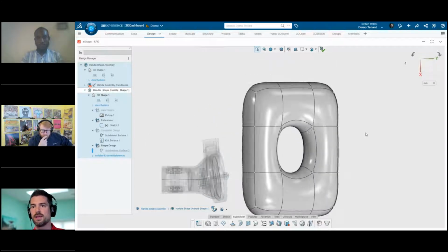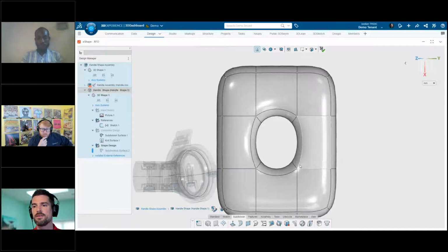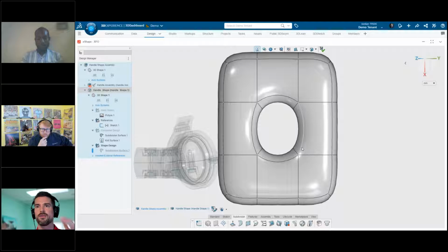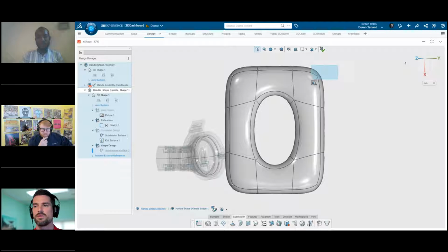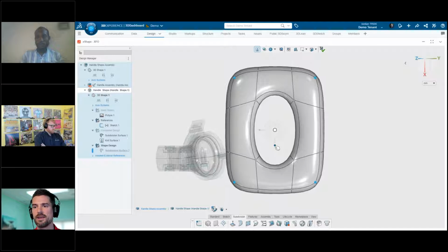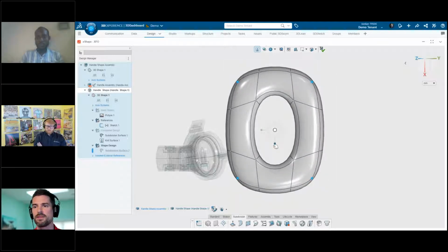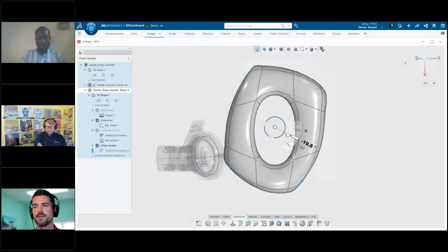Every time we make a modification to this model, all the geometry, you see how smooth it blends from face to face. It has an automatic C2 level of curvature continuity, which in product design is really important. That just ensures that there are really smooth transitions from one face to the next. And I can manipulate this little robot on screen. This is the main UI interface right here. If I drag an arrow, it translates the geometry. If I rotate the ring, it rotates it.